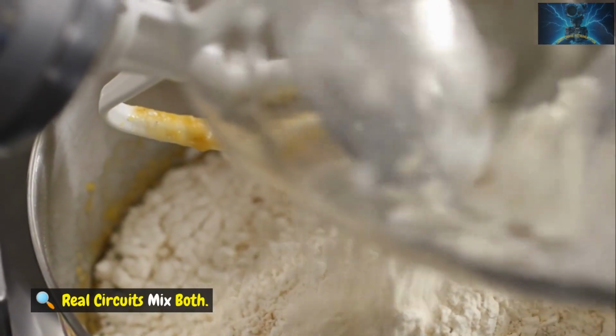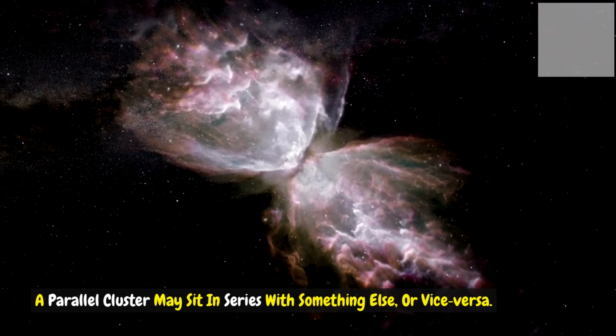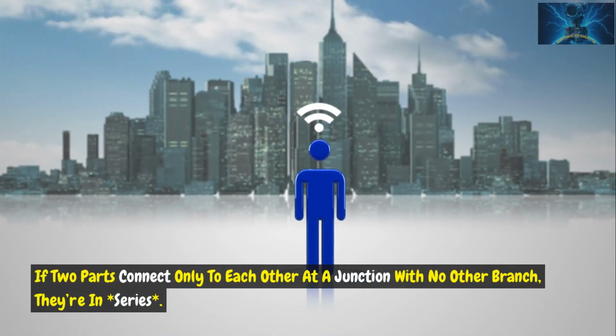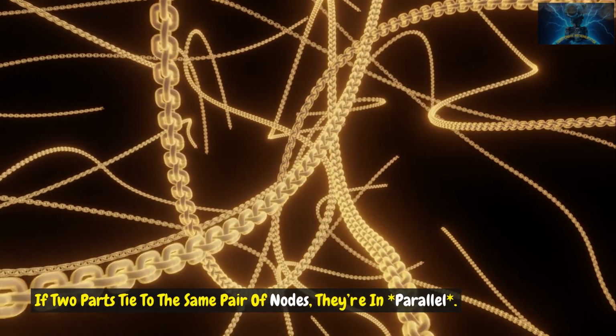What makes a circuit series parallel? Real circuits mix both. A parallel cluster may sit in series with something else or vice versa. If two parts connect only to each other at a junction with no other branch, they're in series. If two parts tie to the same pair of nodes, they're in parallel.